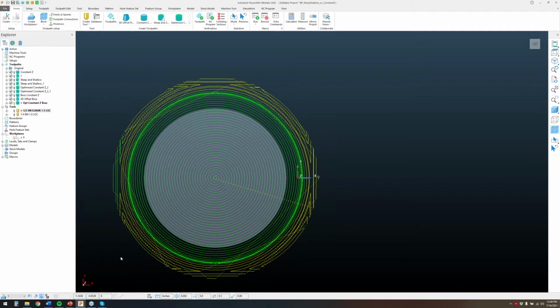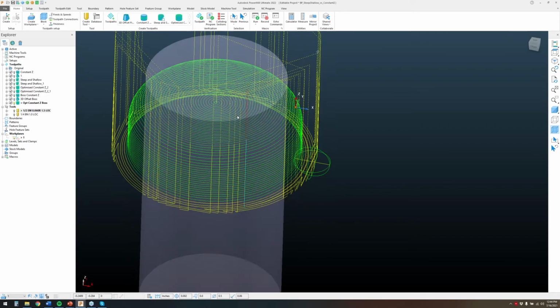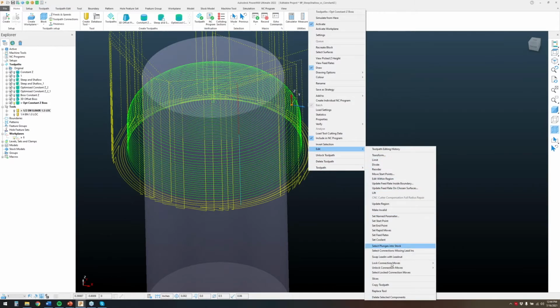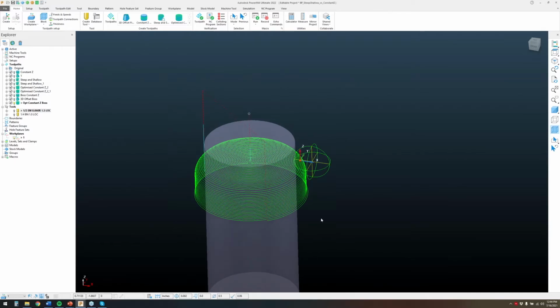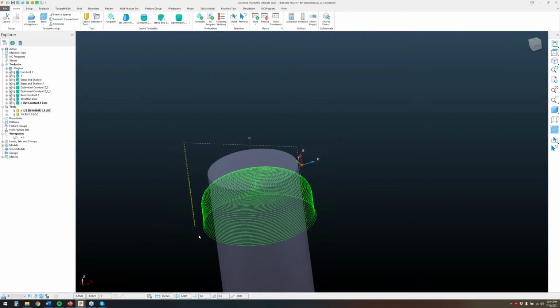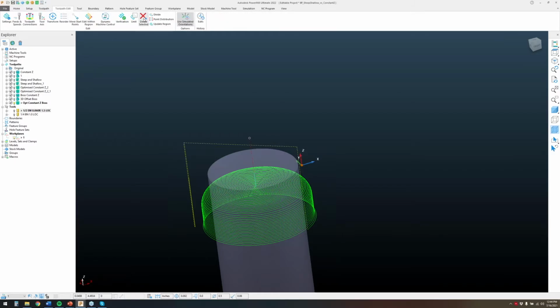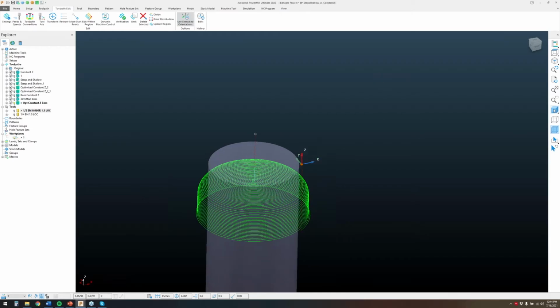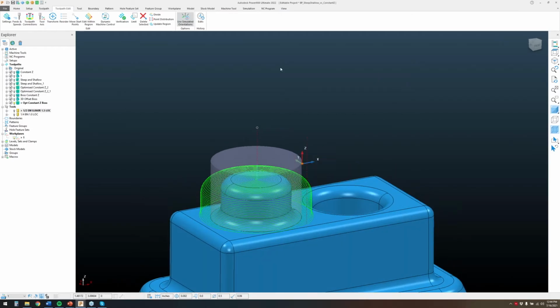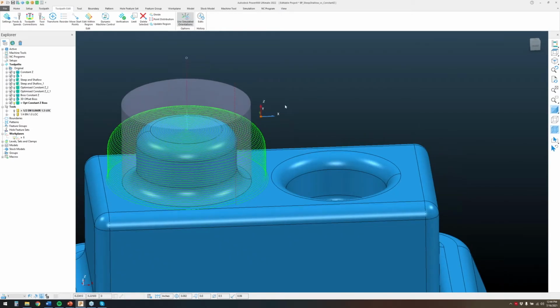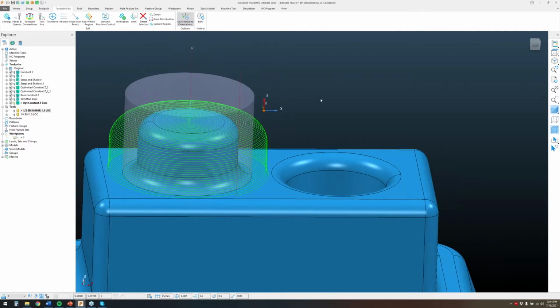And this, guys, is the cool thing about PowerMill, because you can easily modify the toolpaths by right-clicking, going over Edit, Delete Selected Components. You can also go to the Toolpath Edit tab in the ribbon bar and click on Delete Selected. So we turn the model back on, and now we have a clean spiraling toolpath for that boss.